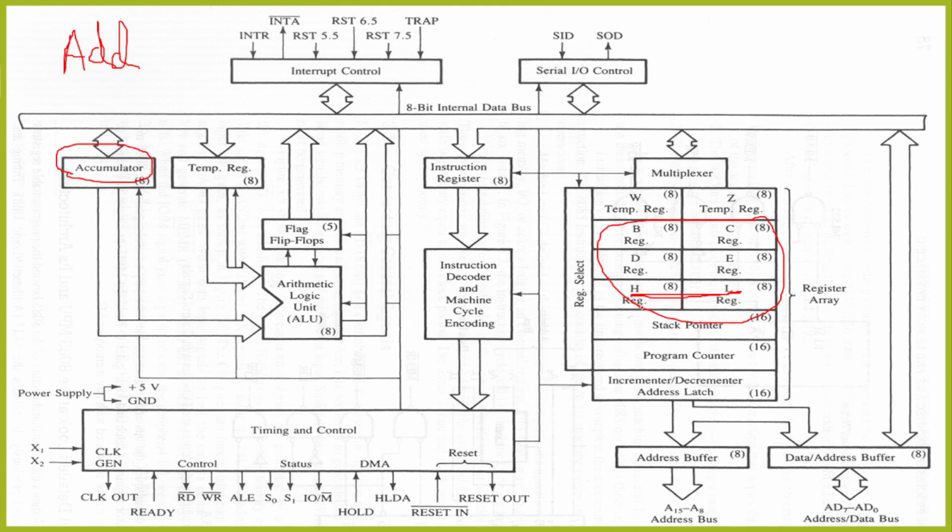There is an instruction in 8085 to perform 16-bit addition. Even though the 8085 is an 8-bit microprocessor and the ALU has 8-bit size only, we can perform 16-bit addition, double addition: DAD register pair, DAD with B or D. At that time the HL will act as accumulator.